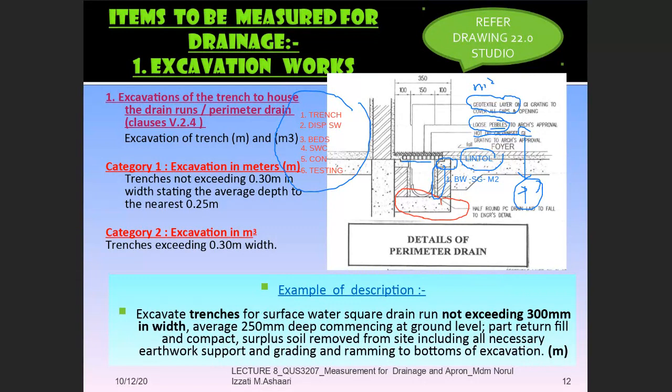Okay, so basically it's not only 6 items to be measured, but you have to consider brick wall, you have to consider plastering in meter square, lintel in meter cube, formwork for the lintel in meter square, GI in meter square, loose pebble in meter square, section S, and geotextile in section D in your SMM. Last page of section D, also meter square.